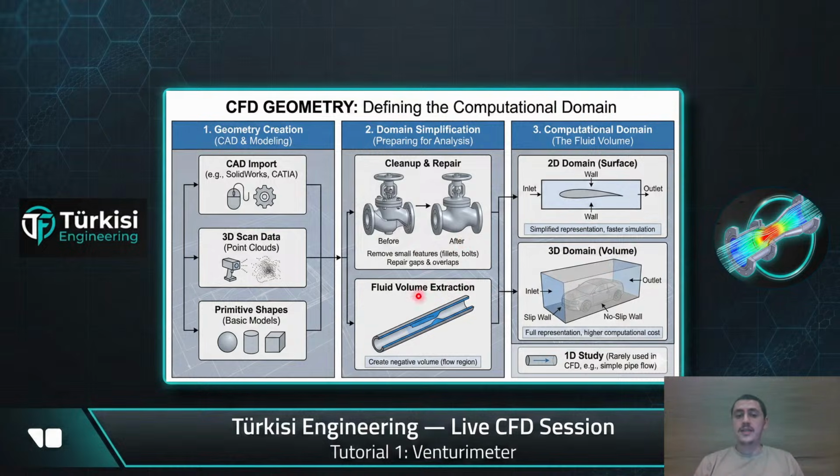After that, you extract your volume, because you don't want to solve anything about your solid. If you are not interested in the solid domain, so you are not doing a structural analysis, you are doing just fluid dynamics, a pure CFD solution, though heat transfer is sometimes included. Let's say we are doing a single-phase fluid dynamics problem. So we need to extract the internal volume, because only the volume of the water or any fluid will be of interest.